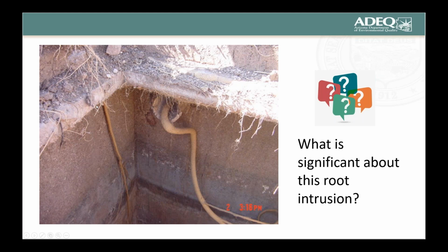There's moisture coming out. Roots actually appear to be able to sense water vapor, and they will try to go back to its source, and they'll send out roots and then expand them. So there probably needs to be some treatment around the outside of this tank to inhibit root growth.